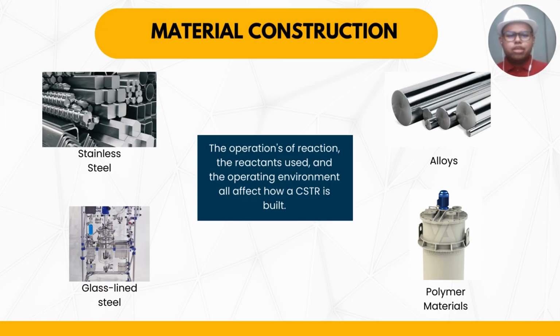Hi, my name is Nur Hakim Shahid, and I will explain about the design of a reactor in the context of material construction and instrumentation and monitoring. Firstly, I would like to explain about material construction, which typically in industry are stainless steel, glass-lined steel, alloys, and polymer materials.